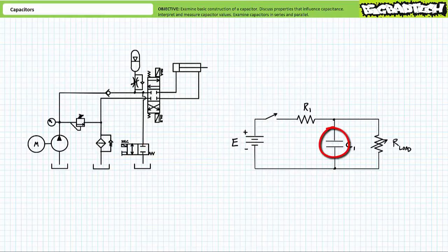This being said, note that capacitors include a small gap between the plates. As you are no doubt aware, current does not flow through an open. You might therefore initially assume that a capacitor blocks current flow. However, we'll learn that an uncharged capacitor experiences a brief surge of incoming displacement current during the charging process as charges accumulate on the plates. Additionally, a charged capacitor can supply a momentary burst of outgoing displacement current as charges are shed from the plates during the discharge process. We'll examine how the electrical properties of the circuit under inspection influence the intensity and duration of these bursts of current during the charge and discharge process in the very near future.